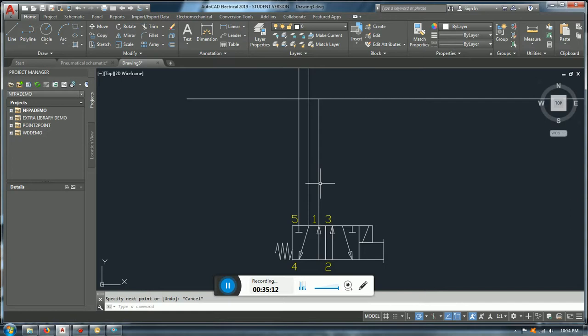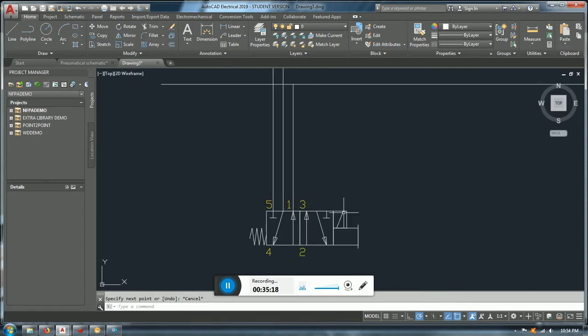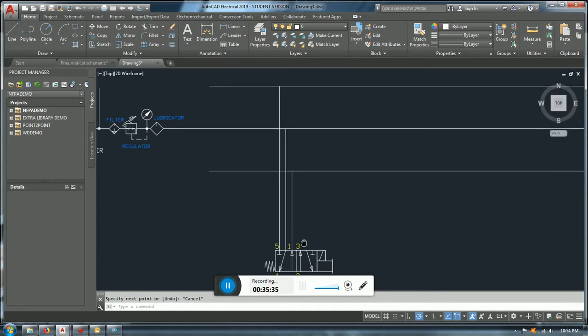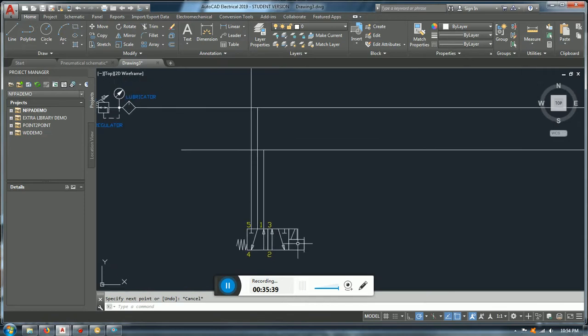That one is sending the air here, and that one is sending the air from the manifold to the solenoid valve. If now you manually or with electricity connect that, it moves here. Now this one is still the main pressurized line. Now that one doesn't do anything, and now that one is the one that is going to exhaust all this air. Okay, awesome, works fine.